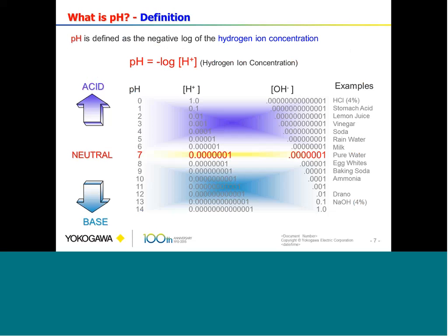So what is pH? Basically, what are we measuring when we measure pH? What makes a liquid acidic or basic? Well, another name for a pH electrode is a specific ion electrode for hydrogen. When we measure pH, we're actually measuring the hydrogen concentration of the solution. You know that little P in pH? Well, that stands for power. It's a Latin word, pondus, but it means power. And the H is obviously for hydrogen. Therefore, pH is the power of the hydrogen component in the process.